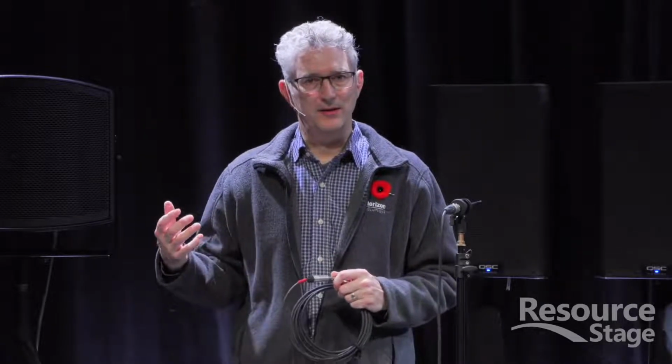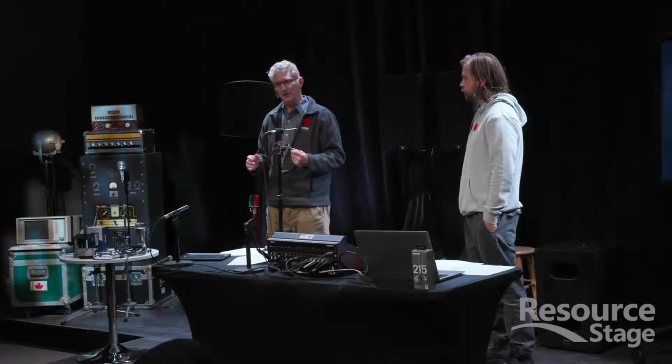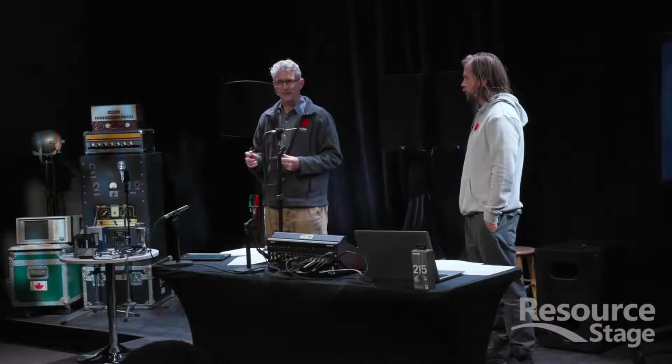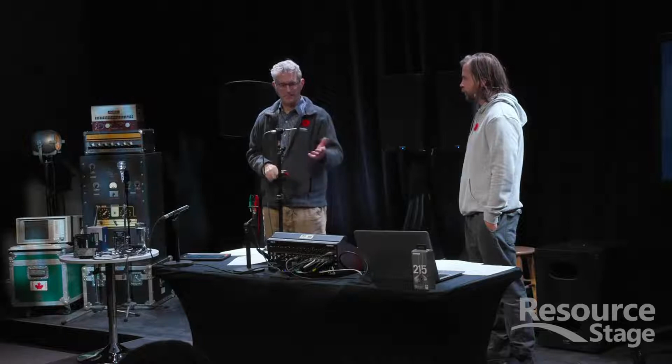Speaker cables can generally run longer than 25 feet. They can be run several hundred feet, depending on the gauge of the cable, how large the cable is, without interference. The reason it can run that far without interference is because it's running at a way higher signal than this would be. This again is meant to connect an instrument, which is at a very, very low level. After the mixer, it goes to a processor and then an amplifier, which boosts that signal significantly, and so it's not as susceptible to noise, at least not audible noise.